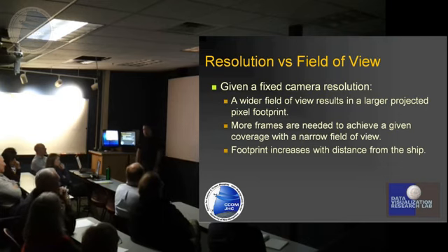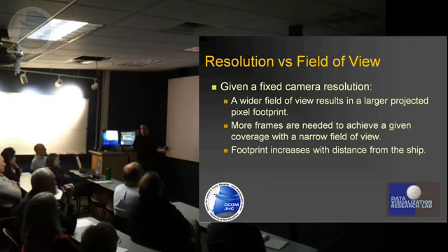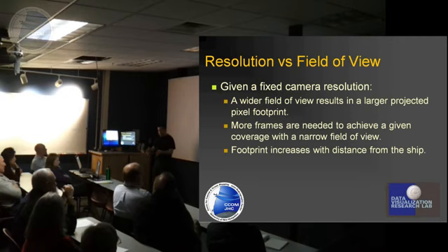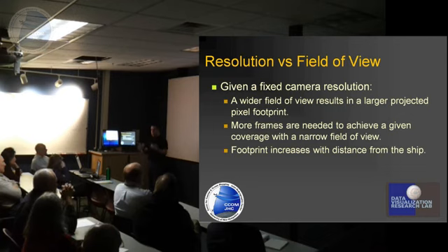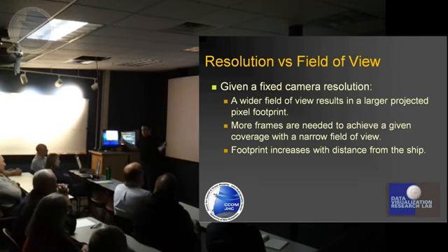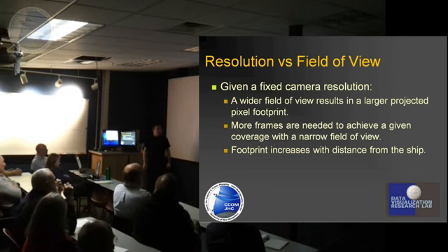Now, how do you pick what camera and how to set it up that you want to use? Because depending on if you zoom in or zoom out, that determines your field of view. Either you get a wide field of view or a narrow field of view. Now, of course, if you zoom in, it's like you're looking through binoculars, you see everything clearly, so that means that you can get a higher resolution for stuff that's far away. But when you do that, you're also getting a narrow field of view.